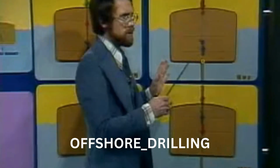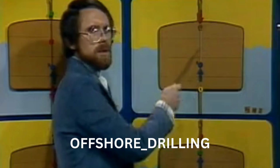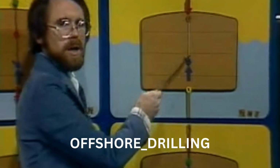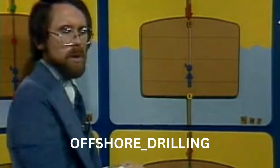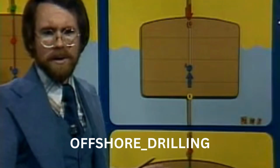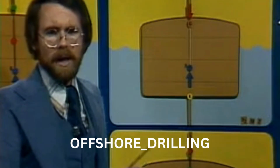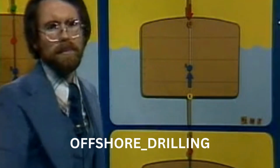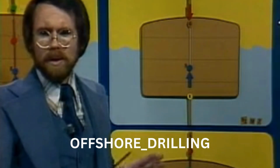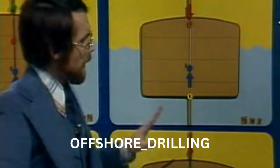When the vessel is in a stable position, the keel, K, center of gravity, G, and center of buoyancy, B, will be in a straight vertical line. The forces of buoyancy and gravity will be acting in opposite directions and along the same vertical line. Since the amount of force being exerted by both gravity and buoyancy are equal, the vessel will rest.